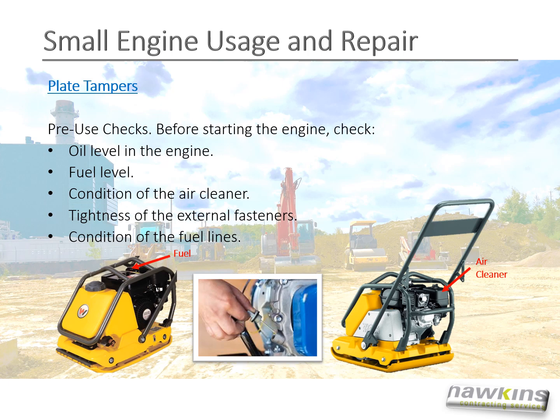Plate tampers. Pre-use checks. Before starting the engine, you should check the oil level in the engine, fuel level, condition of the air cleaner, tightness of the external fasteners, and condition of the fuel lines.